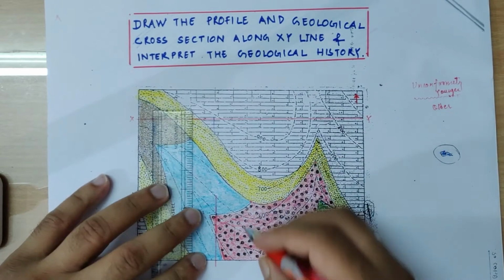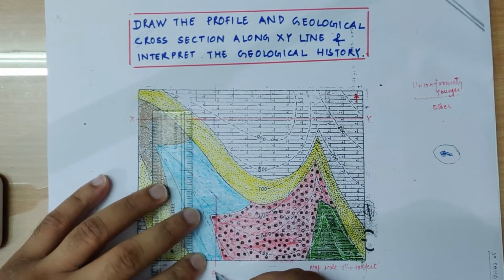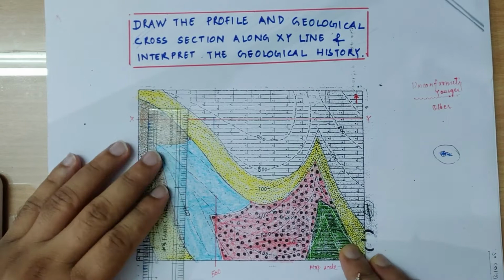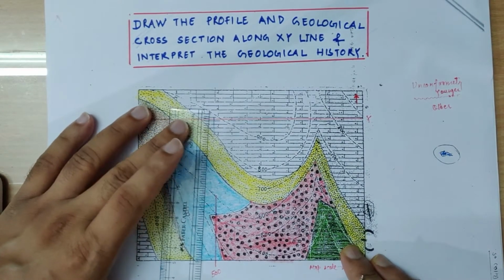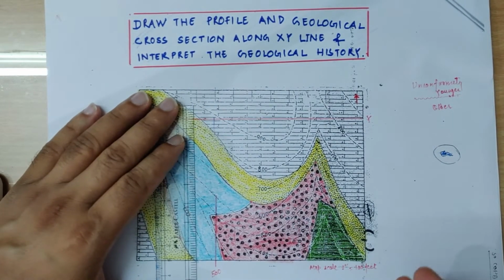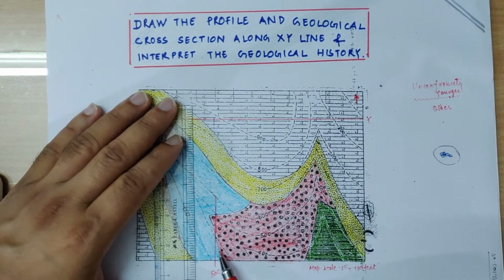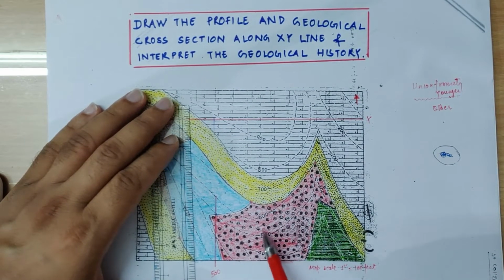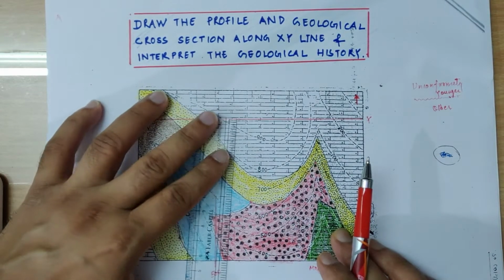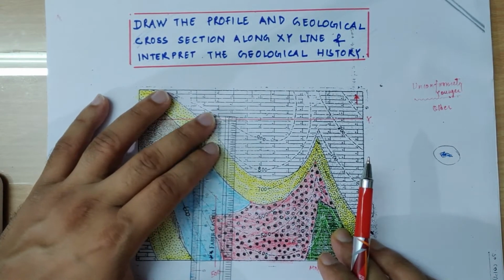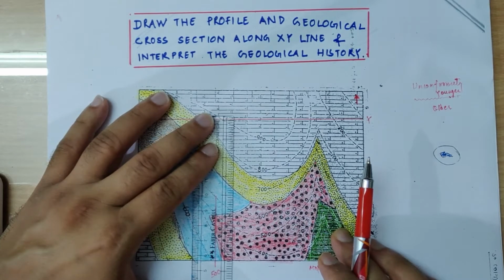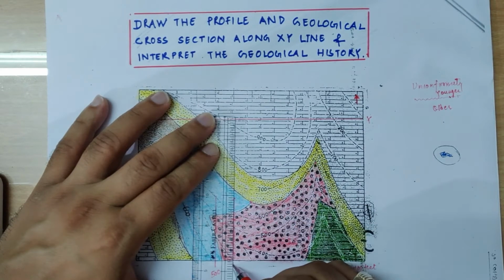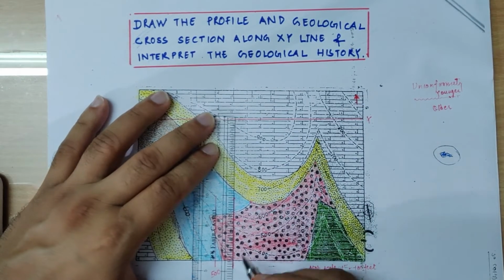The value of this strike line is 500. Now in order to know the dip direction and dip amount, we need another strike line with successive higher or lower value. So this one is 500. Now we need either 600 on the same trace or 400 on the same trace. 400 is not intersecting that trace, but 600 is intersecting. So we can draw one more line parallel to the earlier strike line, and that is going to give us the second strike line of value 600.